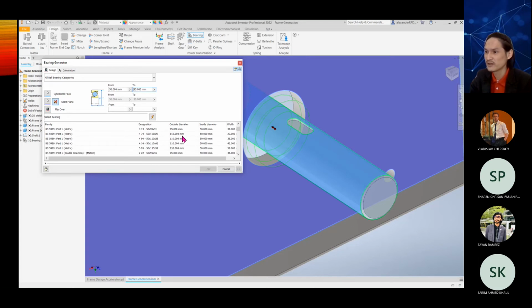So you can select the one that you want. But because they are the same, if you want to adjust, that will be slightly difficult. Okay, so you can select. Now my shaft, this one, the size is different from the other one. So the bearing they select for us will also be different. We may not have an 85 over here for this small shaft enclosure. So normally we don't open all, we limit.